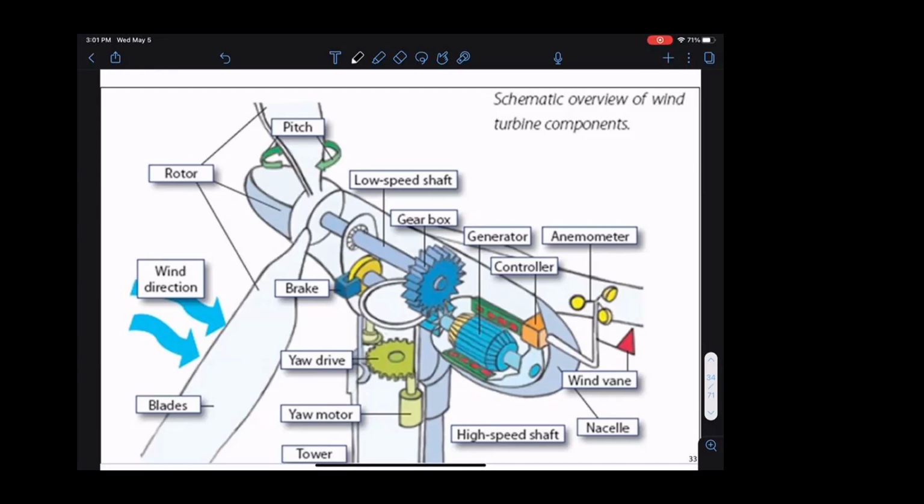For example, if you have wind, let's say you're in the Midwest on a summer night, what you see is the price of electricity is often negative. The negative price means, please consume electricity, I'll pay you. That means we can't get rid of power that easily. We have to pay. If it generates too much power, I have to pay people to take that power. And even worse is when you have a fault. If you have a fault, wind farms are large. You have transmission lines running around this wind farm.